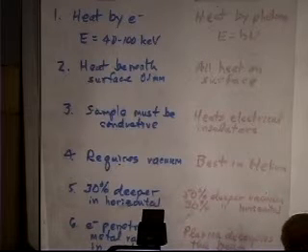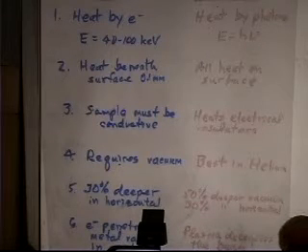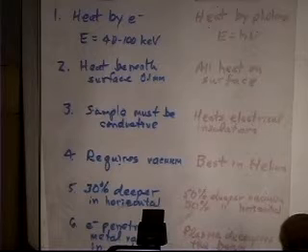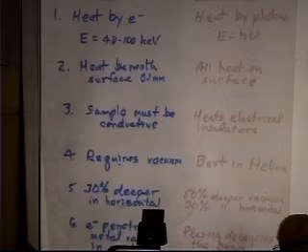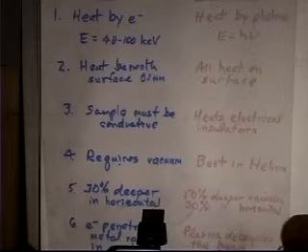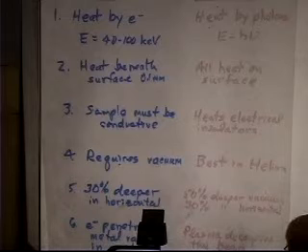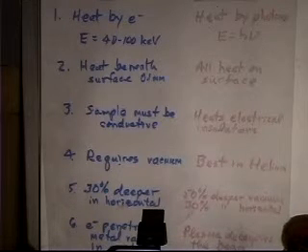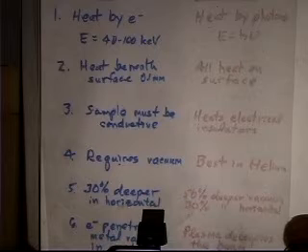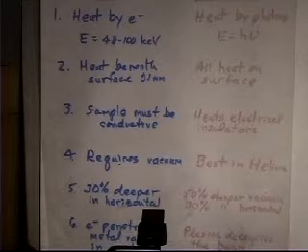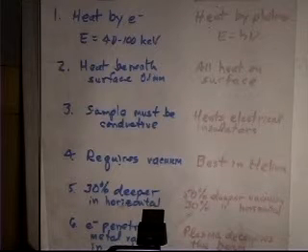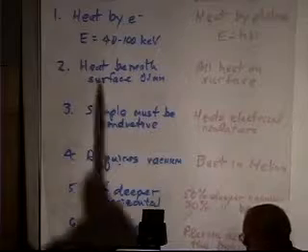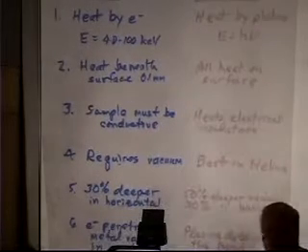For the laser, with very low energy photons hitting the surface, everything is on the surface for a conductive material. Now, if I have a non-conductive material, like a glass, the light can go through it, so I could heat beneath the surface of a partially opaque glass or a ceramic with a laser. But for metals, which we're usually interested in welding, it's all surface heating.